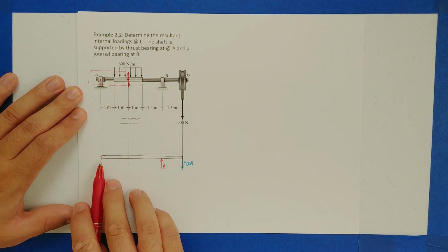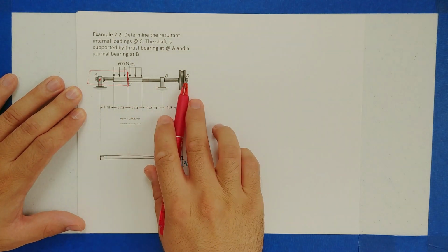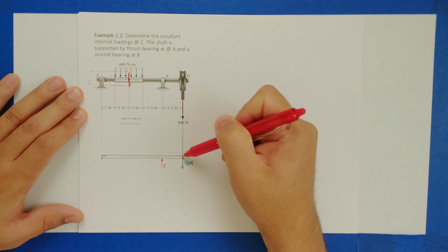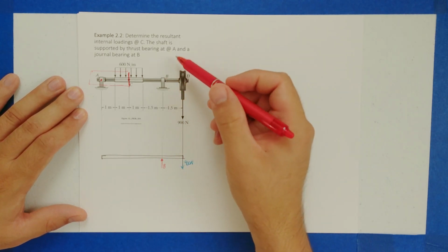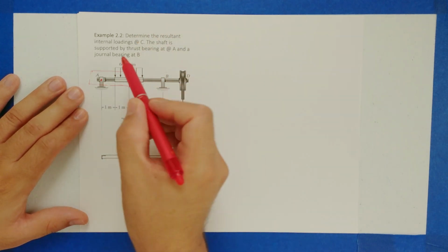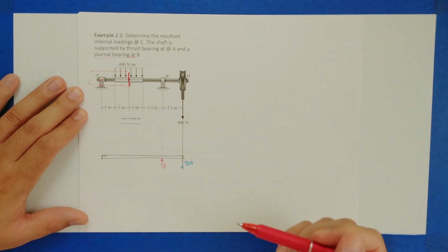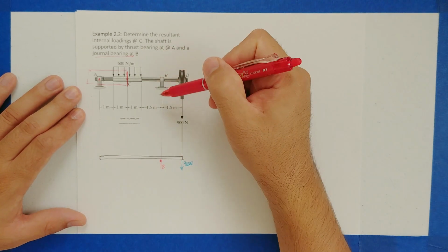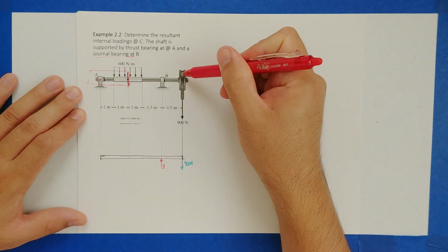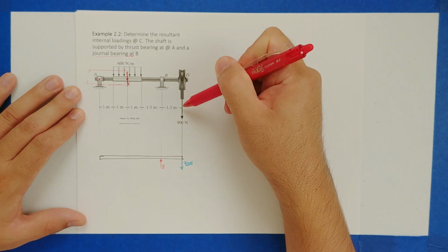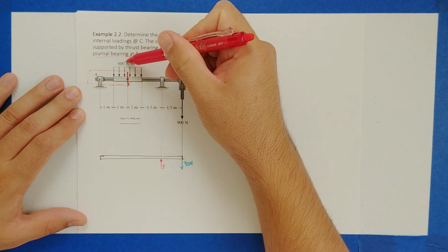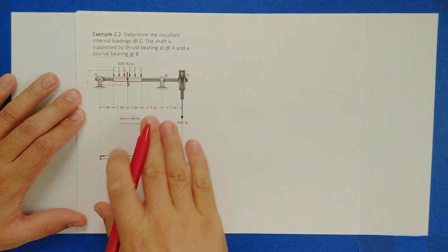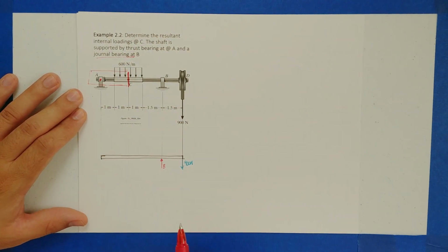So what I've done over here is already started a little bit the free body diagram of the shaft. I know I have a 900 Newton force pointing down over here at D. At B, I have a bearing. Remember, the bearing at B is a journal bearing, so these bearings are not going to limit any thrust in this direction, only in the vertical direction. Since I have 900 Newton force going down here on the right side, and I have a distributed load going down on the left-hand side of this bearing, I'm going to assume that this guy is going to keep this shaft in equilibrium by moving up.